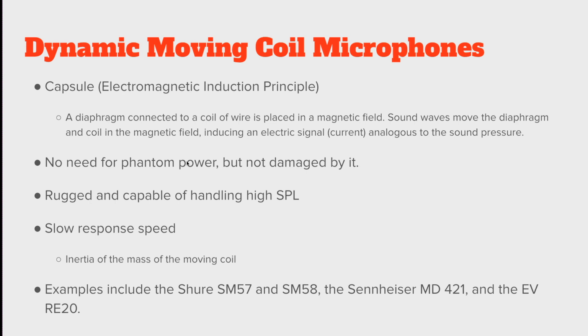So we'll talk about phantom power in a minute. Phantom power, as many of you who have ever worked with a mixer know, there's something called phantom power. It's important to know phantom power doesn't impact dynamic microphones. It won't damage them. They don't require it. There's no underlying principle that requires the use of phantom power for a dynamic microphone.